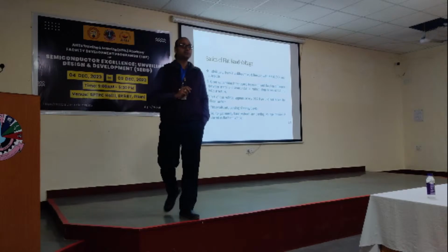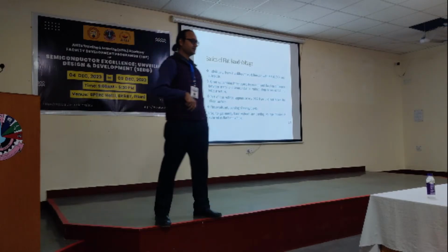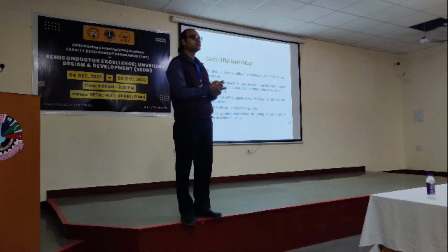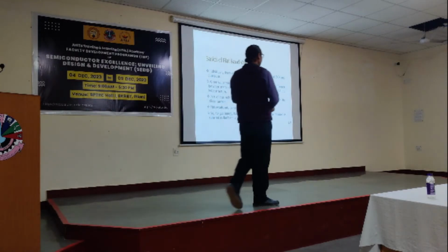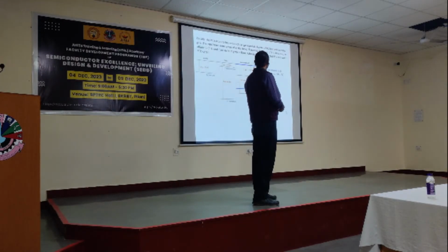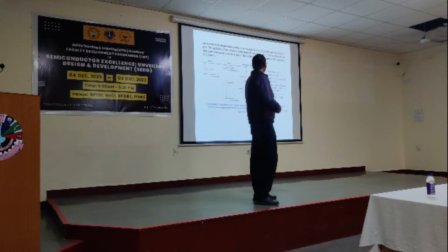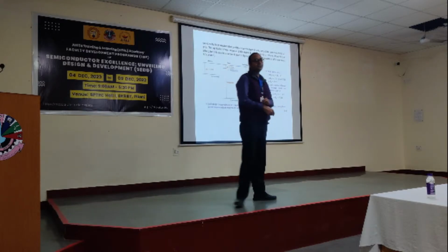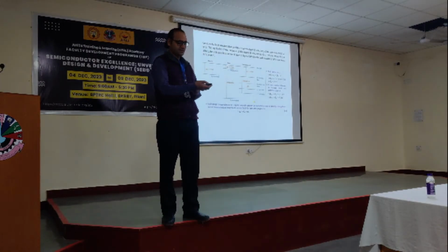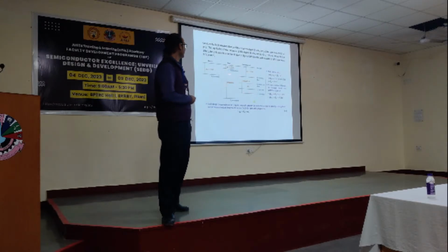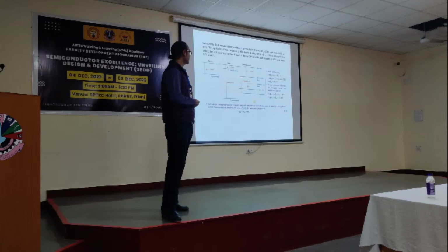Now, what is the other possibility? When we fabricate the structures, there are defects in the oxide. There are charges in the oxide. Now, can anybody tell me, suppose in this structure we have positive charge in the oxide, and my target is to invert the surface, meaning I want electrons at the surface.